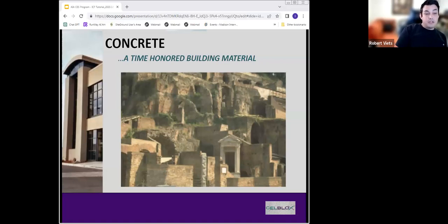And so after about 50 to 60 years after you pour your concrete wall, it will have reabsorbed all the carbon that was created during its manufacturing process. And then after about 50 or 60 years, the concrete is now carbon negative because it will continue absorbing carbon for the rest of its life and permanently sequestering it. So if it's for long-term structures, concrete is actually one of the greenest building materials there is.